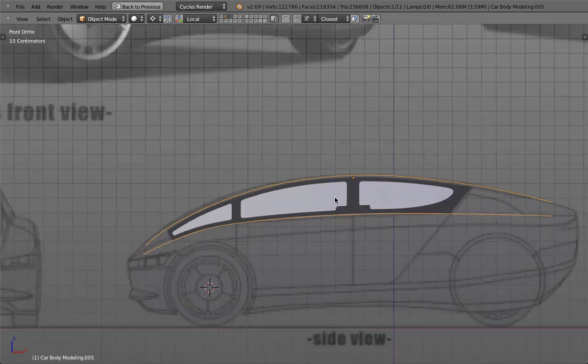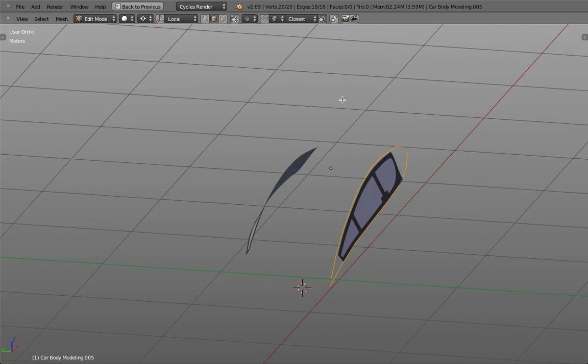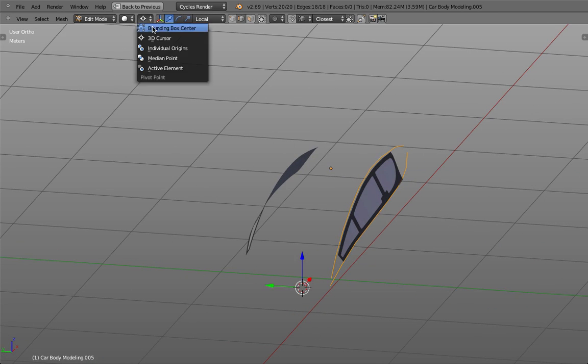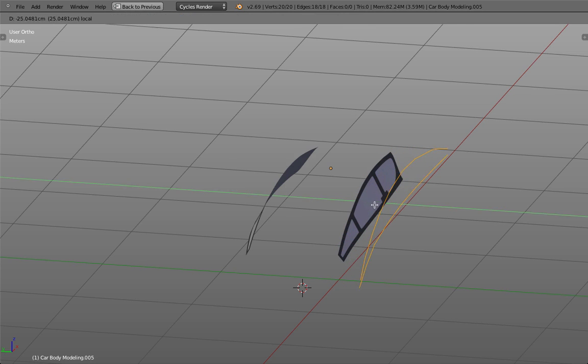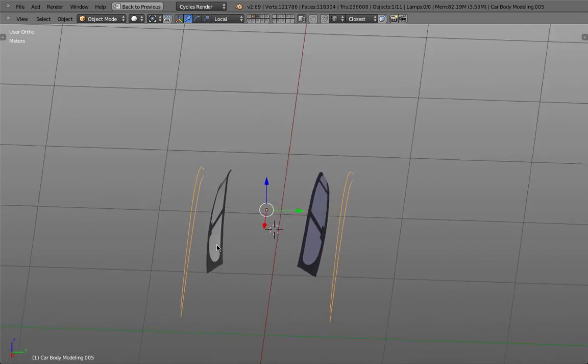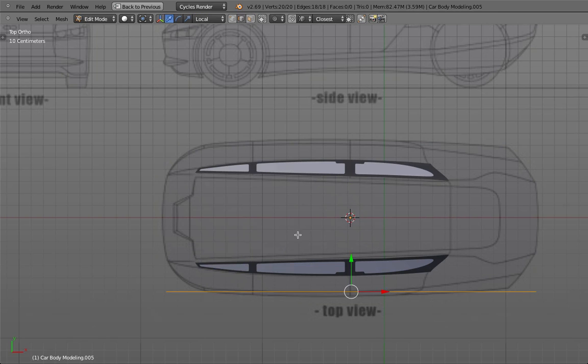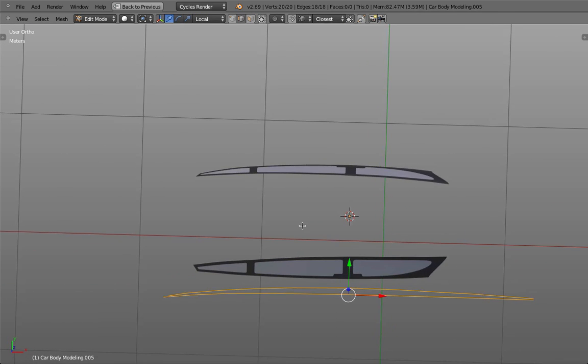So I'm starting to work with curves a little bit. They go into all directions. So to clean this up a little bit, I select them all, press S, Y, and 0, and maybe move them away a little bit. So I have kind of like something like this. And then actually with those curves, I can press E and Y, press E, scale and Y to 0.